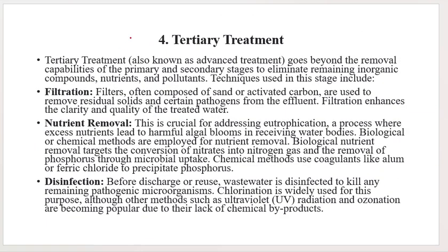Then comes the fourth stage, that is tertiary treatment. This stage is also called advanced treatment. We can also call it the chemical treatment process. This goes beyond the removal capabilities of the primary and secondary stages to eliminate inorganic compounds, nutrients and pollutants. Through primary and secondary treatment, we have removed almost all organic pollutants. However, there are still inorganic pollutants present in the wastewater. Those inorganic pollutants will be removed through tertiary treatment.